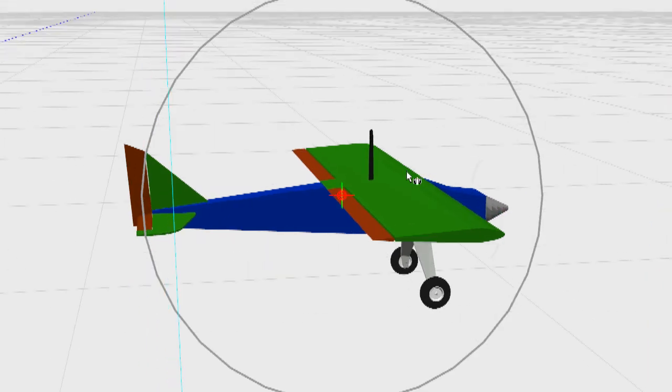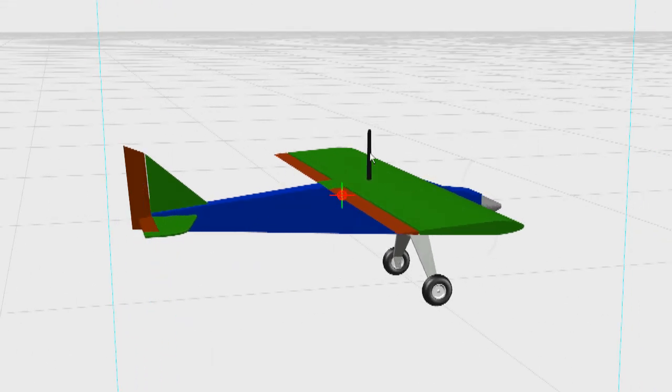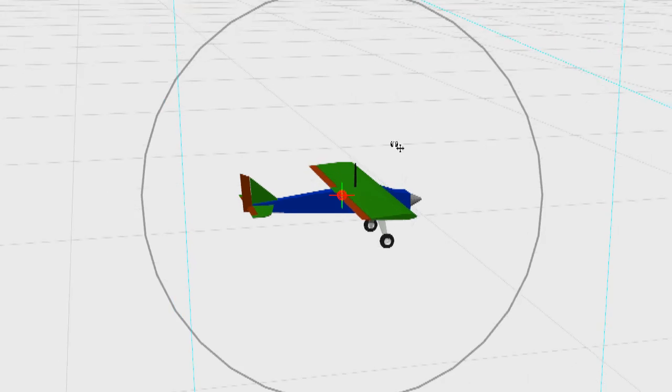Now, a lot of people think the gain represents some sort of strength or the sensitivity of the antenna. And what it really is, it determines the pattern. And you have high gain and low gain antennas. Now, a 2 decibel omni antenna like this would be a low gain antenna. The benefit with low gain is the pattern goes all the way around it. The field of view, if you like, is extremely wide, and with an omnidirectional, it's in all directions around it.